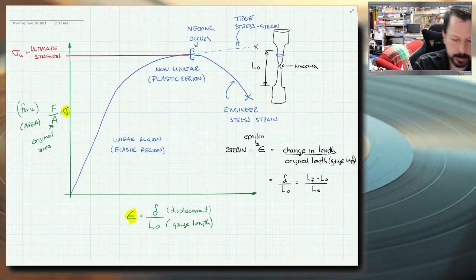I think in the bearing example we did yield strength. But the ultimate strength includes some of this permanent deformation, permanent change in size or shape or geometry, from this part. And so you might not want to deal with ultimate strength in your designs because you probably don't want things to change shape in your machines you're working on or your buildings that you're designing.